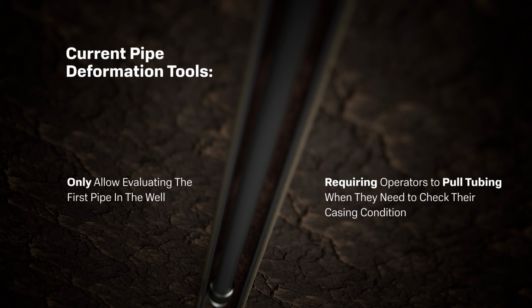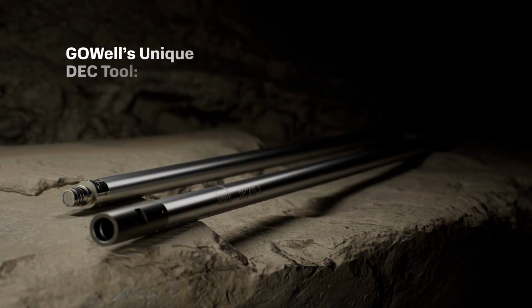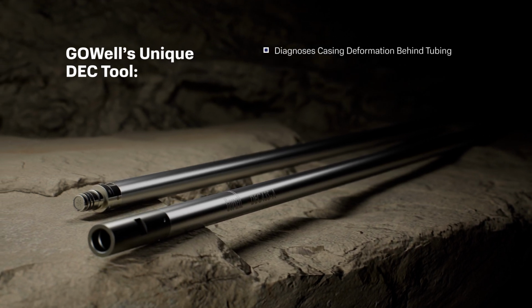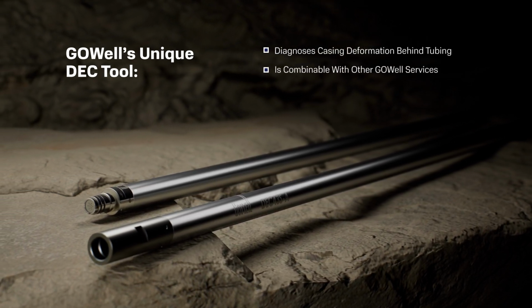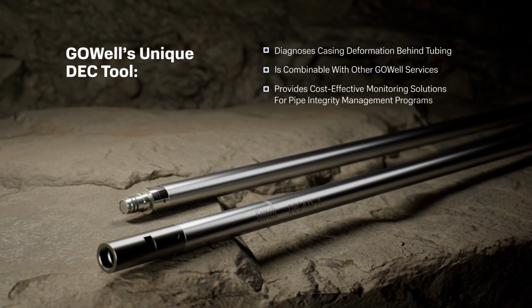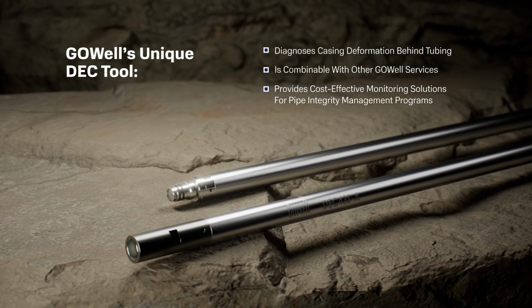Current pipe deformation tools only allow evaluating the first pipe in the well and cannot see through to the second pipe, requiring operators to pull tubing when they need to check their casing condition. GOWell's unique DEC tool diagnoses casing deformation behind tubing, and the technology is combinable with other GOWell services such as multi-pipe wall thickness measurements to provide cost-effective monitoring solutions for pipe integrity management programs.